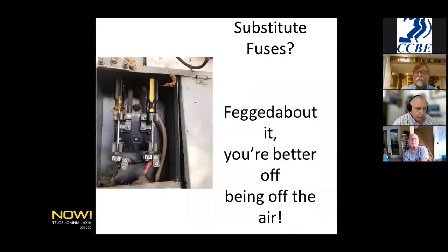This engineer sent this to me, with a question, wondering what the blow rate was on that fuse, whether it was a fast blow or a slow blow. I think it's more of a fire generating fuse. You don't want to do something like this. People do, and unfortunately, they'll do this and then walk away and forget about it, or put the cover back on and forget about it.